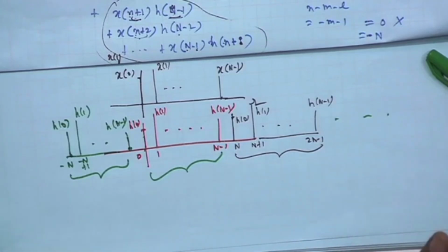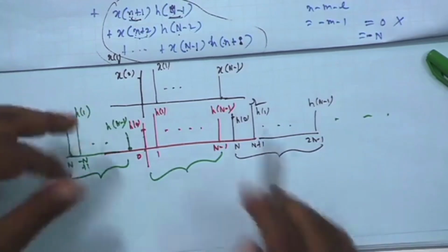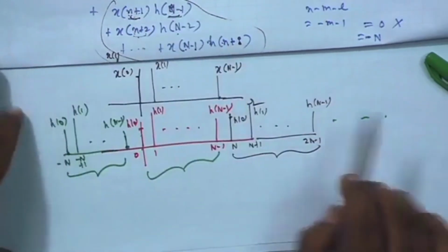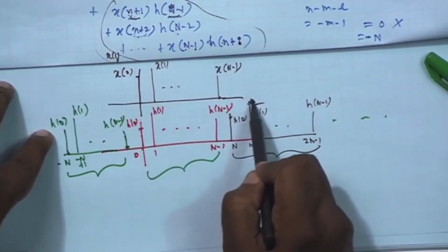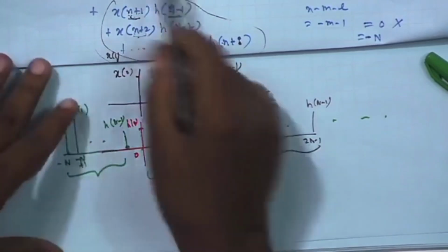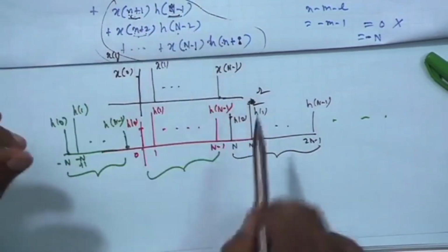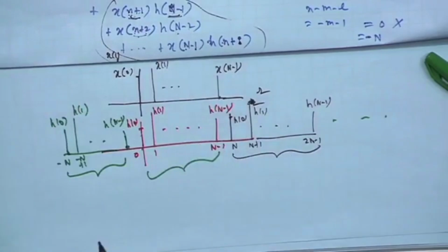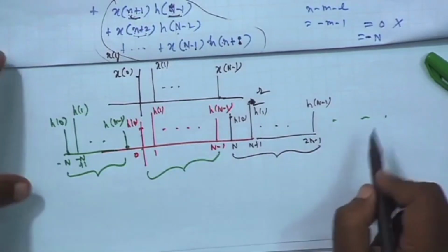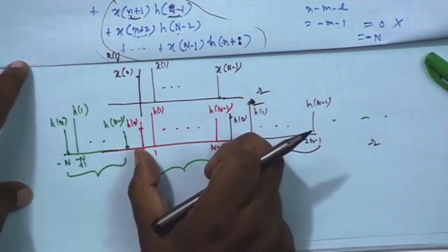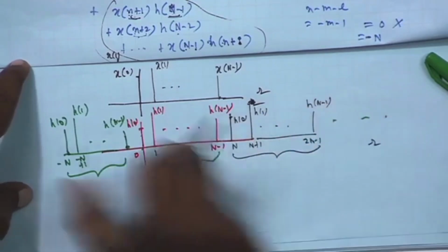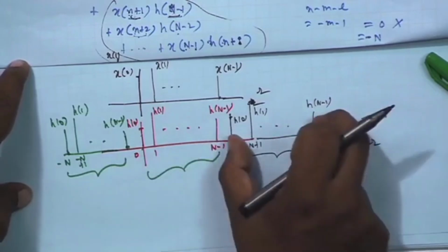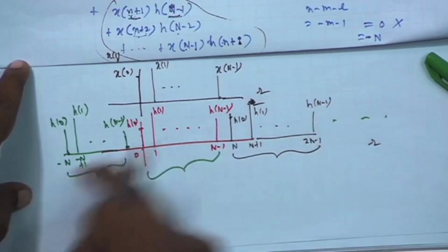If you are doing circular convolution between two sequences graphically, I am suggesting a rule and then we will verify that it gives you this expression. So, what is the rule? One of the sequences you hold as it is, as a function of r, not n, because you want to find the convolution at a fixed small n. The other sequence also you make a function of r, but if one period is given from 0 to n minus 1, you repeat it again. One block, the same block again, so you get a periodic sequence.